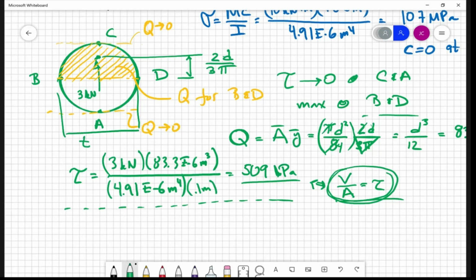So really, like when you have those shear pins that we talked about early on, or a bolt, honestly, it's still this type of shear stress. This is a little more accurate description of it, right? It's actually not going to be uniform over the cross section. It vanishes up at the tops and the bottoms and is max at the middle. Okay.